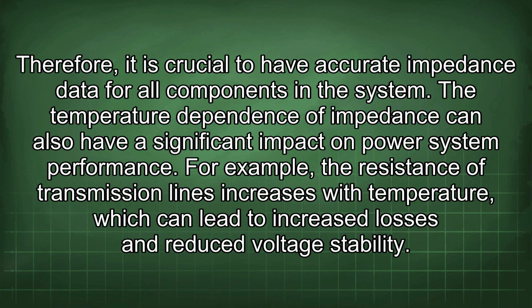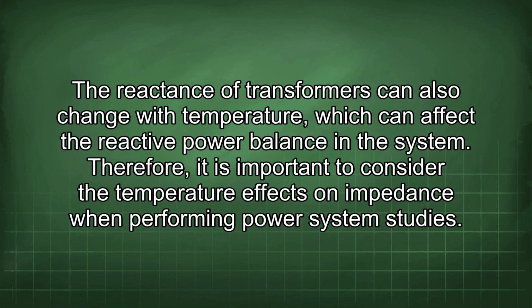The temperature dependence of impedance can also have a significant impact on power system performance. For example, the resistance of transmission lines increases with temperature, which can lead to increased losses and reduced voltage stability. The reactance of transformers can also change with temperature, which can affect the reactive power balance in the system. Therefore, it is important to consider the temperature effects on impedance when performing power system studies.